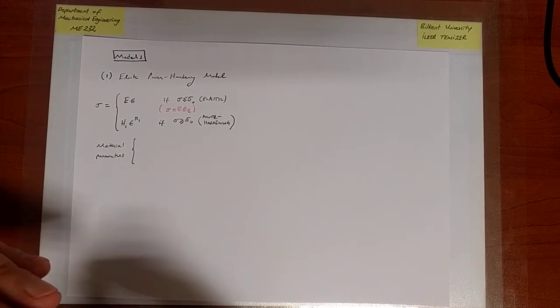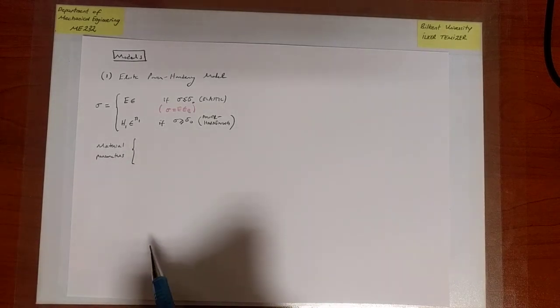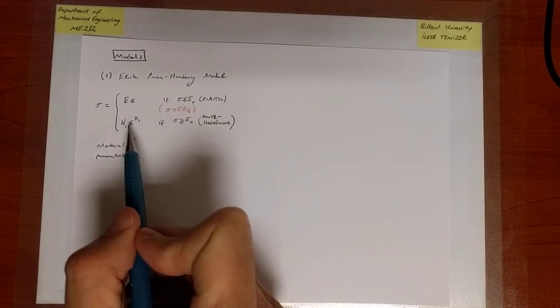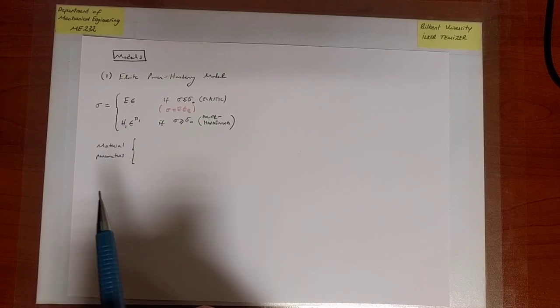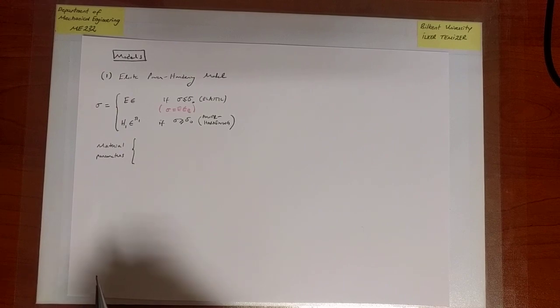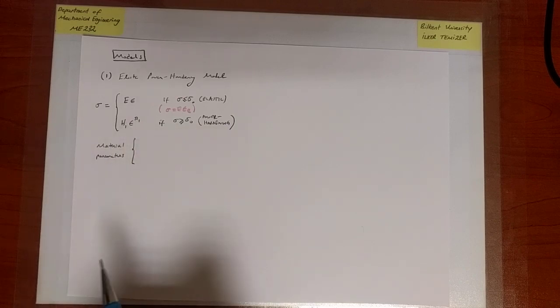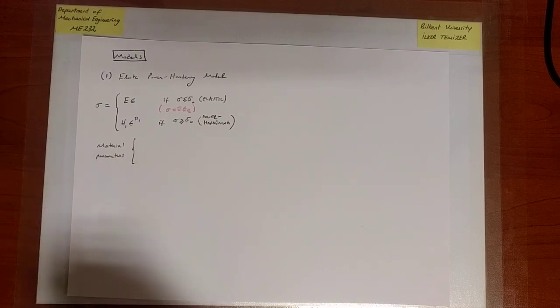And having said that, at this point you may want to just roll back and have a look at that modeling idea I talked about earlier when we tried to replicate data points with a good model that is able to fit that curve. So that model is going to eventually have some free parameters. This is a very simple model with only visibly two parameters. It turns out there aren't two, there's less. But in any case, we don't know yet the values of these parameters. We have to determine them such that eventually the stress-strain curve that is predicted by these two equations is able to replicate the data as closely as possible. So determination of those parameters is an issue on its own.